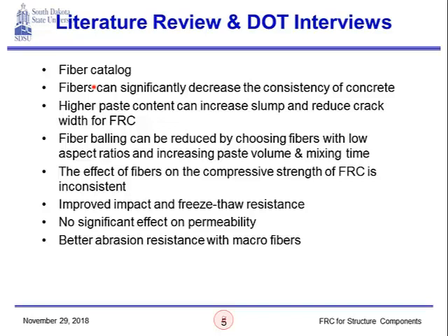Now, another finding is the fact that higher paste content can increase slump and reduce crack width for FRC. Of course, there are also some disadvantages of using higher paste content, so this is something that also should be taken into account. It's a way to increase slump and reduce crack width, but we should always keep in mind the other problems that are associated with higher paste content.